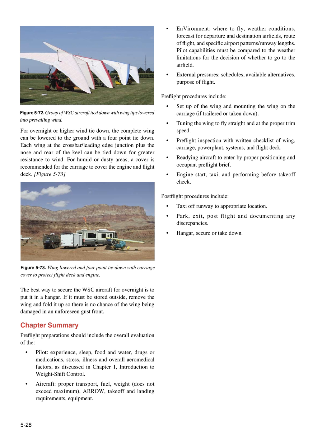Chapter summary. Pre-flight preparation should include the overall evaluation of the pilot: experience, sleep, food and water, drugs or medications, stress, illness and overall aeronautical factors, as discussed in Chapter 1, Introduction to Weight-Shift Control. Aircraft: proper transport, fuel, weight does not exceed maximum, aero, takeoff and landing requirements, equipment. Environment: where to fly, weather conditions, forecast for departure and destination airfields, route of flight, and specify airport pattern/runway lengths. Pilot capabilities must be compared to the weather limitations for the decision of whether to go to the airfield. External pressures: schedules, available alternatives, purpose of flight.